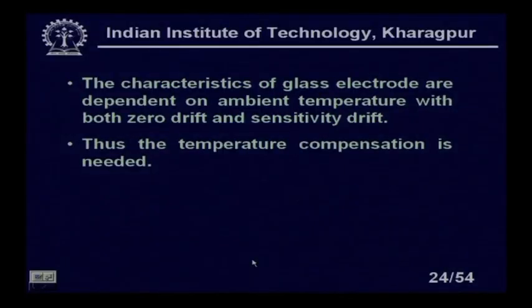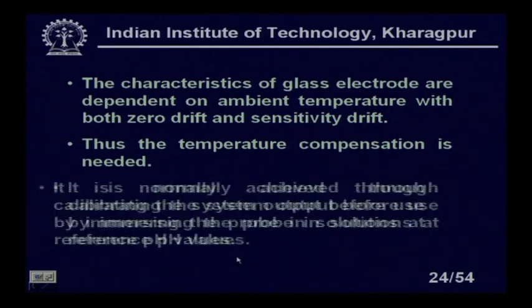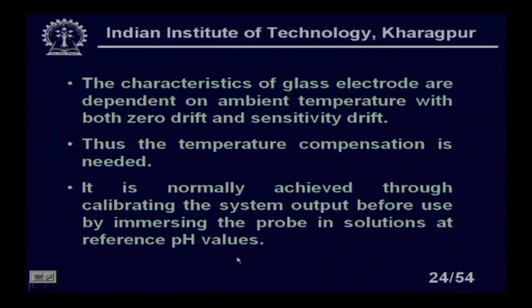Thus, the temperature compensation is needed. It is normally achieved by calibrating the system output before use, by immersing the probe in a solution at a reference pH value. That is a very interesting thing, because with solutions of known pH, I can insert the probe, make the necessary corrections, or have a temperature compensation scheme.